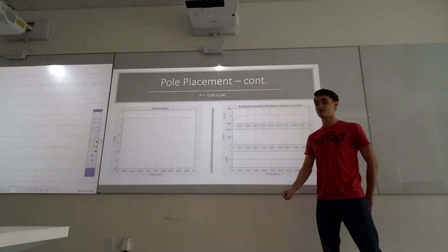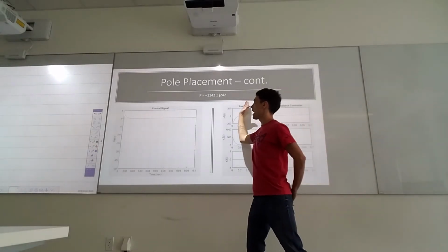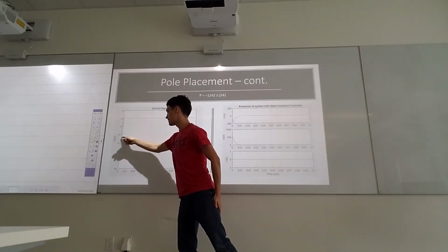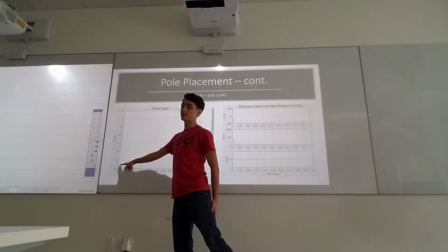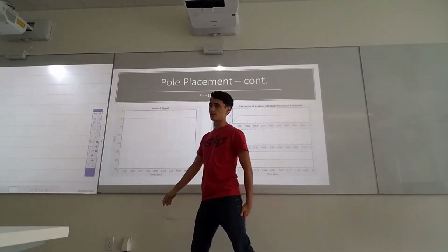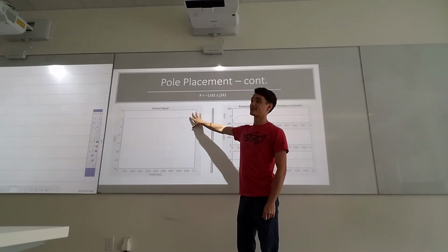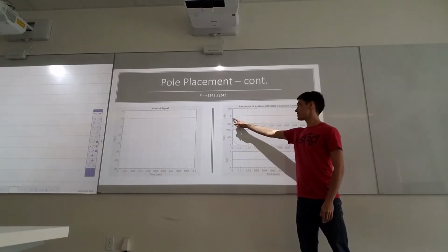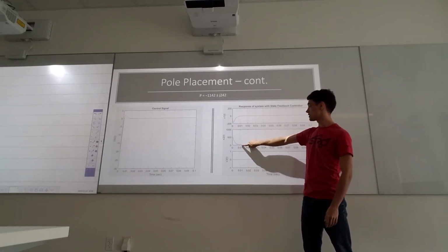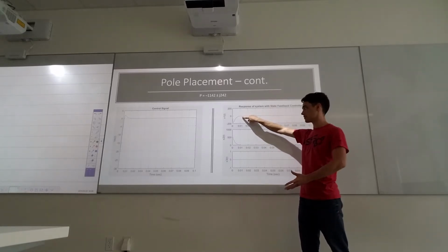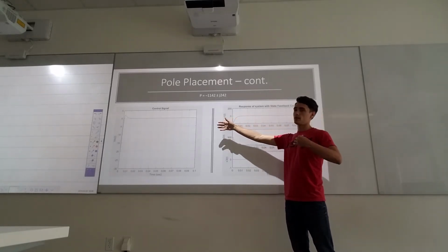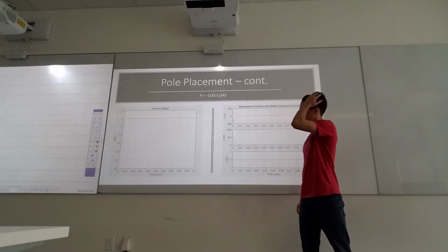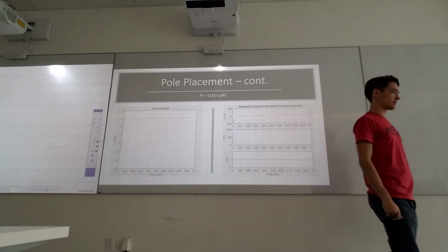So this next controller is much more snappy and aggressive. We move the pole out onto the left-hand plane by 1,000, and you can see the differences. Our controller goes down to about negative 27 volts now, which is much greater. This may or may not work depending on the controllers or motors that are being driven. However, the response is much snappier now. It's actually half of what it used to be, so the settling time is now 10 milliseconds as opposed to 20. But the trade-off here is that the current now almost goes down to negative 200 amps for this much quicker response time.